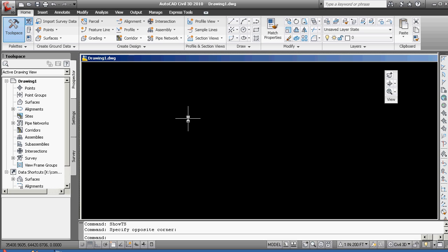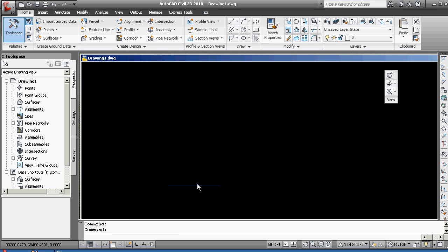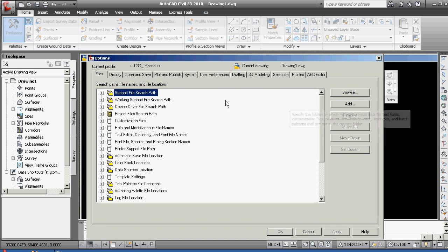somewhat correctly. Remembering in AutoCAD, besides setting your overall network environment, you have to set up your profile. And you set up your profile in this way. You right-click to go to the Options command. And realistically, it's just the Options command is the command you want to learn within AutoCAD. Hit Options there, and you're going to see here in a second a lot of files, a lot of things that you're going to more or less have to access.